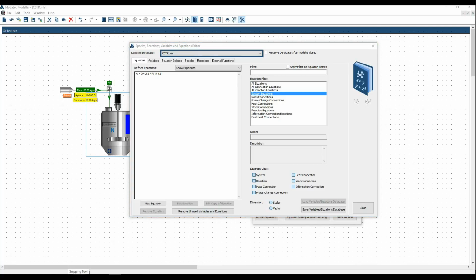If you decide to first create all your model equations from the Main Editor tab, which is also an option, and then add those equations to your model objects, be careful not to press the Remove Unused Variables and Equations button before you add all your equations to your model objects, as if you do that, those equations will be lost as they were not part of any model object. So, to show this option, we will now create all the equations needed for the CSTR capacity system from the Main Editor tab, and then add them to the CSTR capacity system.